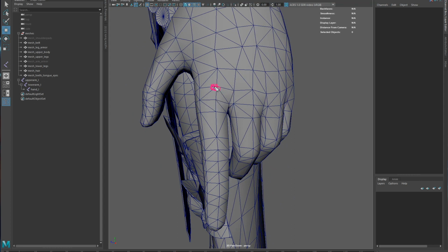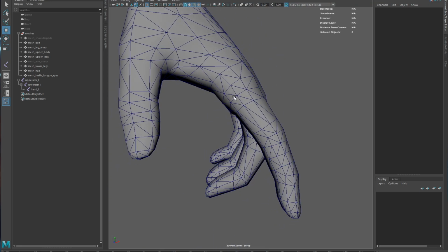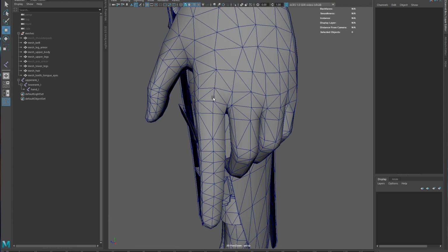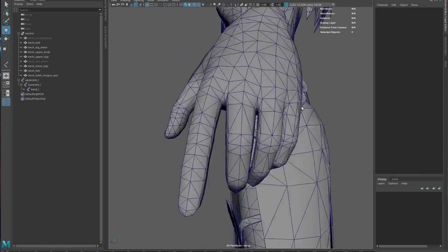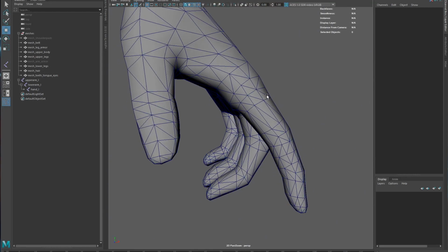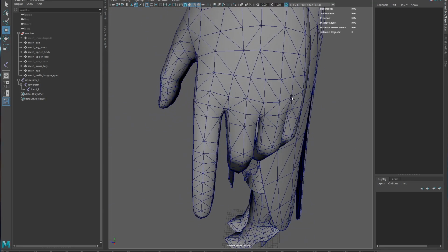I like to put it a little bit higher up because I just think it gives you a more anatomical deformation than putting it a little bit lower. So I would probably put it right up in here instead of here. When you're just looking at loops, it's really easy to just go like, oh, I see 3 loops, I'm just going to put the joint on the middle one. But you also kind of want to look at where the peaks are, and also anatomically, your joints are going to be back up on this one here.